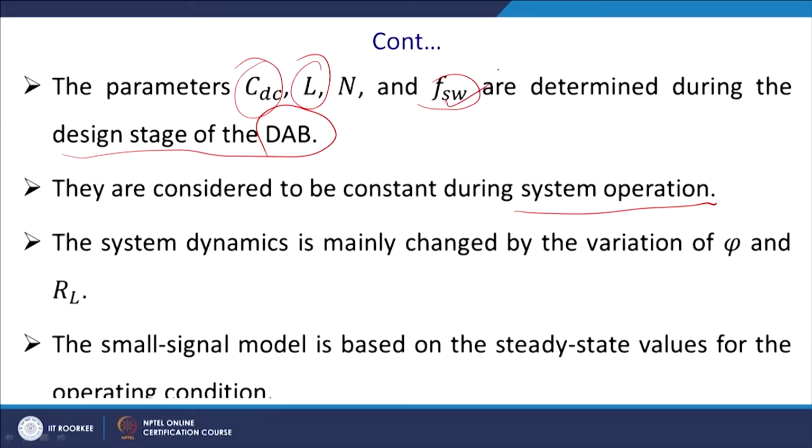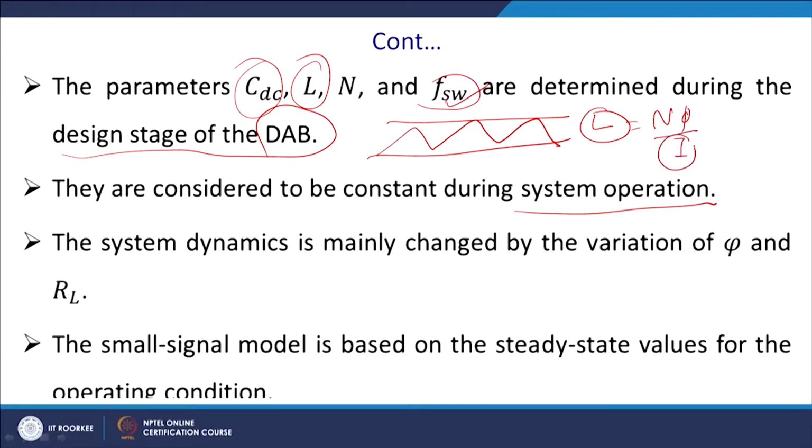So, we cannot use a hysteresis controller, and you know current is always increasing and decreasing in the inductor, and this is the current through the inductor. You know that L equal to N phi by I. Once current is increasing, you may be close to saturation, thus your value of phi may not be changing, and you have a rollover effect.